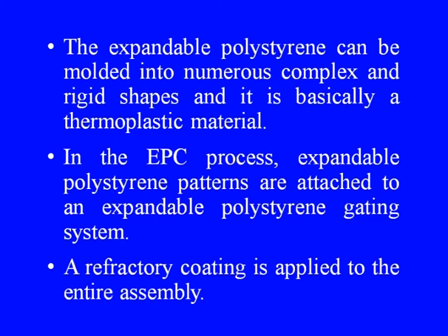A refractory coating is applied to the entire assembly. Once the coating gets dried, the entire foam pattern assembly is kept on loose dry sand in a vented flask. The flask is then vibrated and additional sand is added to it until the pattern assembly gets completely embedded in sand.